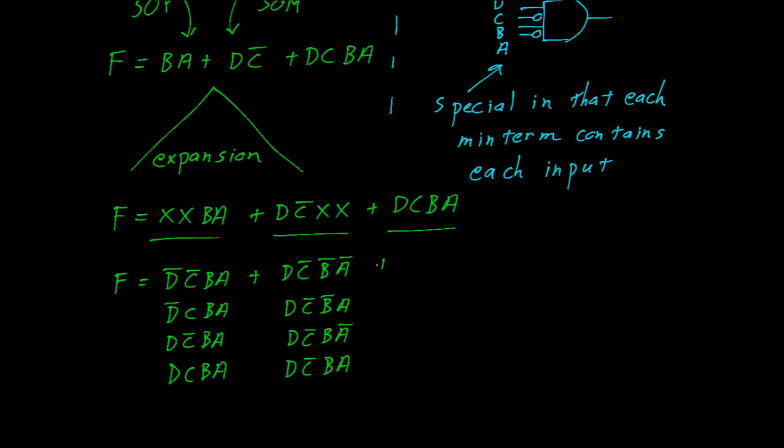And the last term comes down. If you have your handy-dandy note card converter at the ready, you can identify these minterms as 3, 7, let's see, 8 plus 2 plus 1, that's 11, 15, 8, 9, 10, and 8 plus 2 plus 1, I believe that's 11, and finally 15.